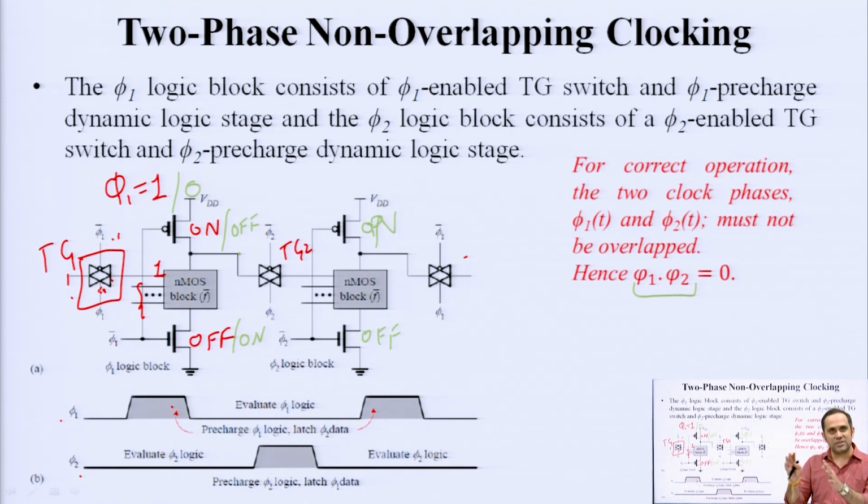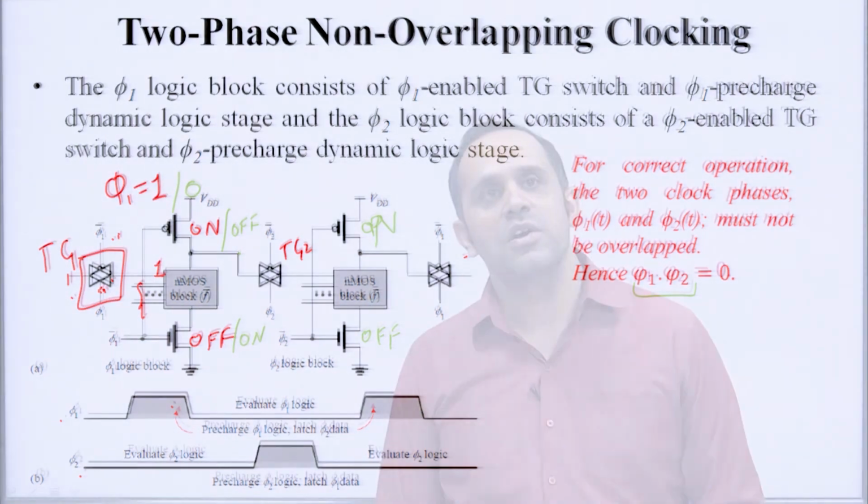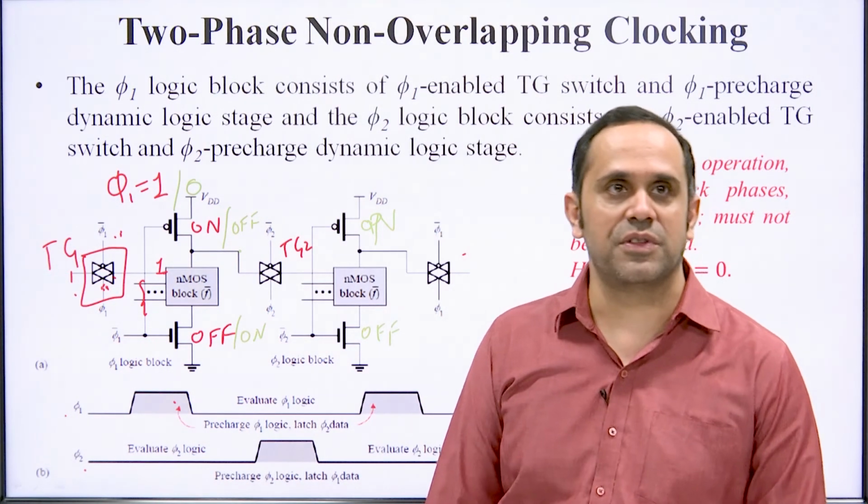So, you are isolating stages from each other and latching data in stages; this might reduce speed a little bit, but signal integrity is maintained. This is known as the two phase non overlapping clocking scheme. In addition to domino logic or np-CMOS logic, this is another way of solving the problem of cascading in dynamic CMOS devices.